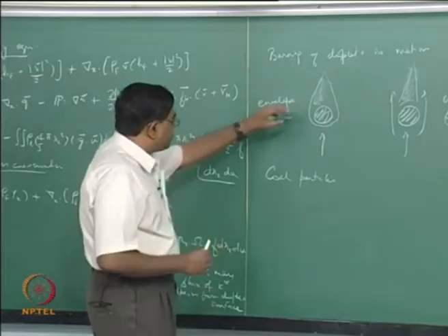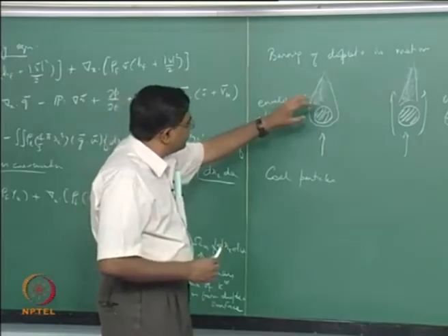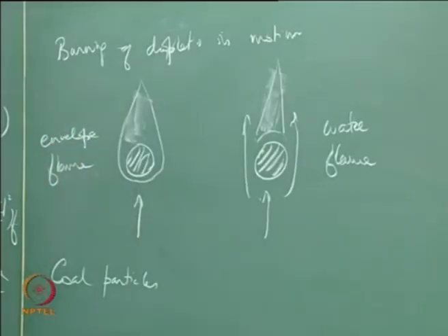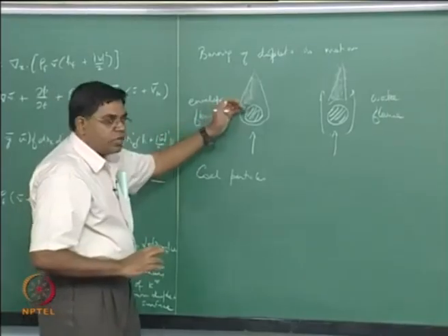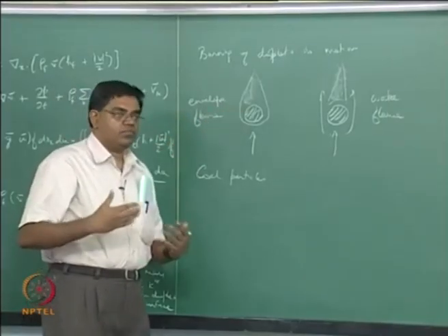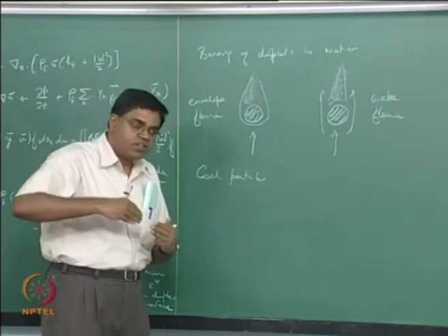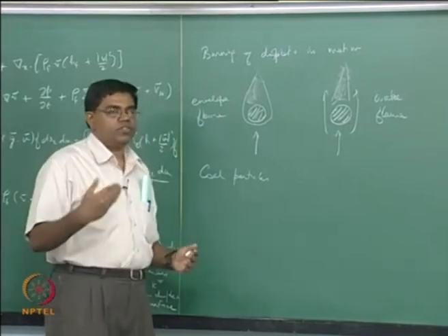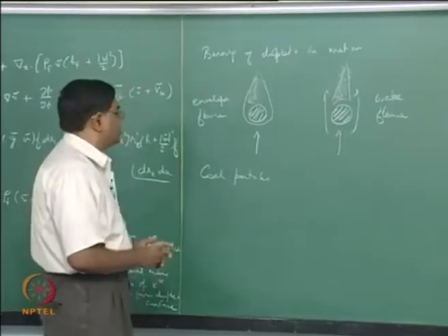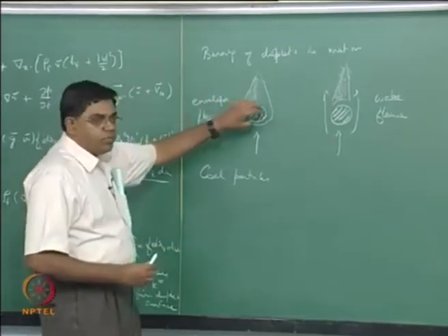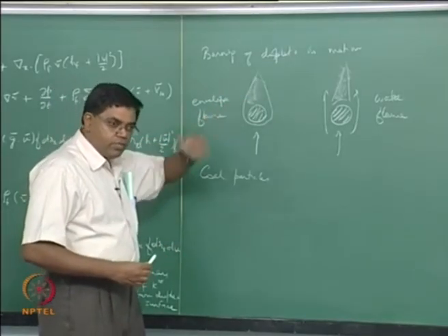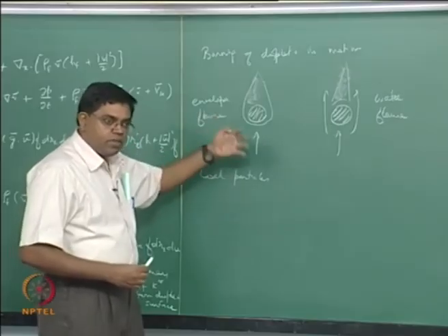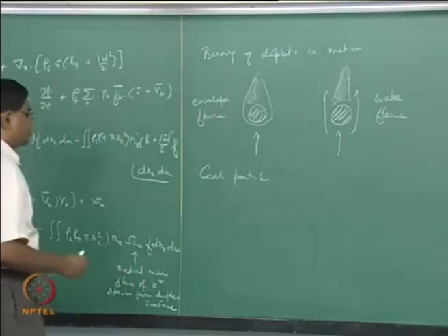But if you still look at liquids, the more volatile ones can actually volatilize from the core and bubble through the less volatile ones, and can cause what's called a secondary atomization. That means it shatters the less volatile ones into smaller droplets, which form from a single parent droplet. So the single parent droplet itself was obtained by atomization, but then you have a secondary atomization because of this. So such things are possible.